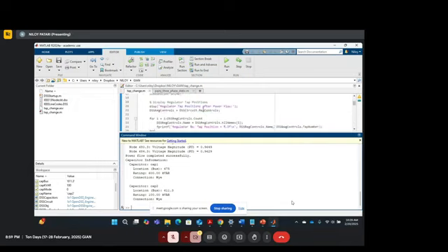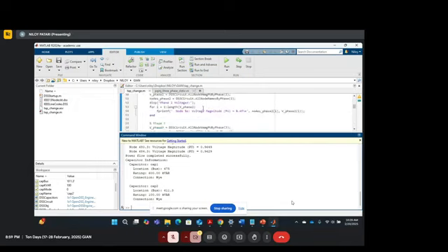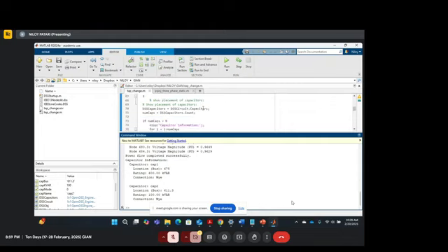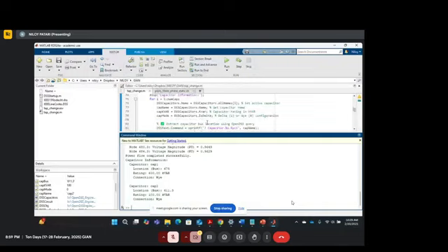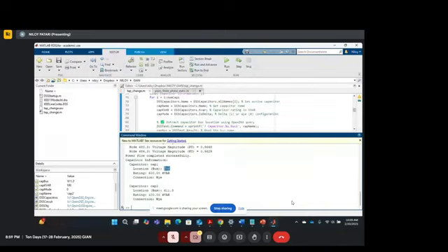And then at the end, I also wanted to know where capacitors are present. So there is this code that I put in that finds out capacitors in the system and displays the names and which nodes they are connected to. It also gives the capacitor information. So there is this capacitor 1, which is connected at 675, in all the phases of 675, 1, 2, and 3, and they were 200 kVA each, right?